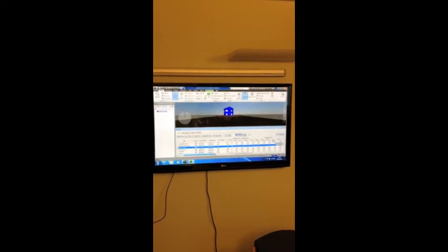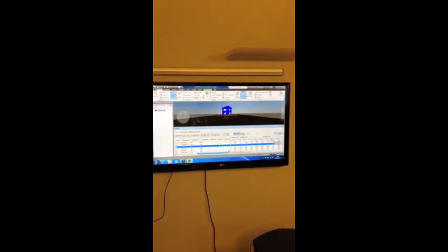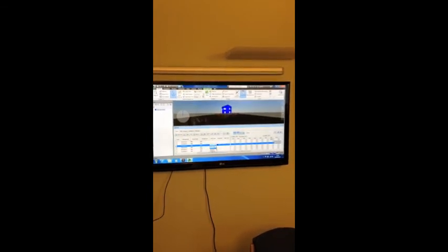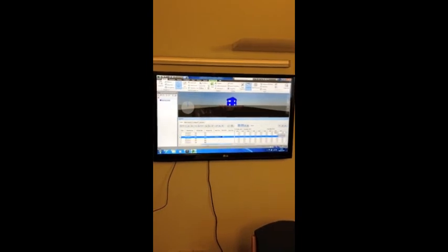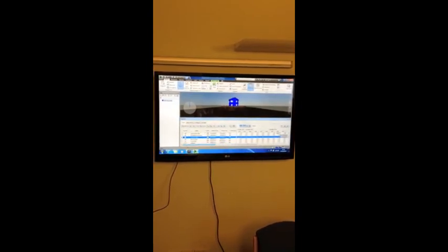You then need to scroll along in the Timeliner and change the task type to construction. There's three different task types: construction, demolition or temporary works, and this is a construction item. And you need to do that for every item in the programme.